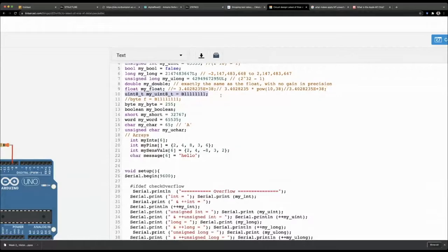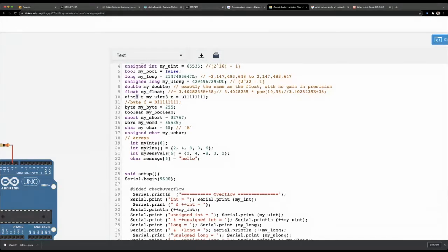You'll find this a lot when you program these Arduinos, and it's very much recommended. So integers is basically unsigned integer, but forcing the integers to take only 8 bits. So it's uint8_t to show its data type. It's inherited from the old C language, but of course works in here, and works with the AVR, so we're perfectly happy to use it. And with the uint, we get access to the actual binary because it's a byte, and we start with a B. So note the difference between using the long, unsigned long, and the binary and other things.